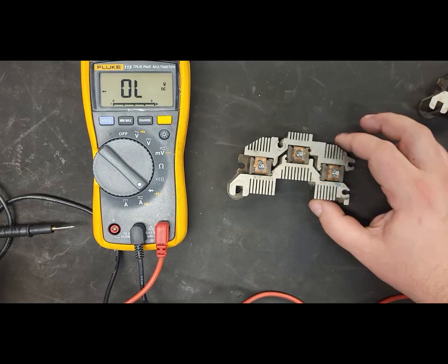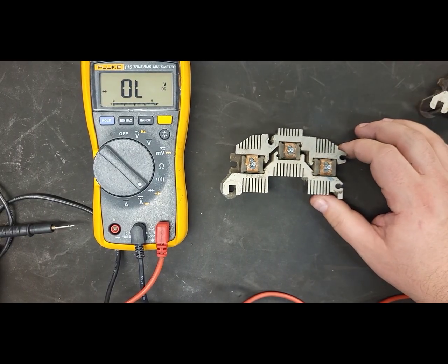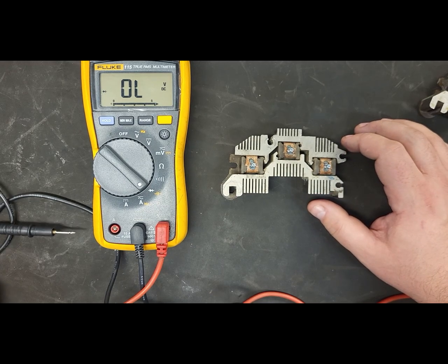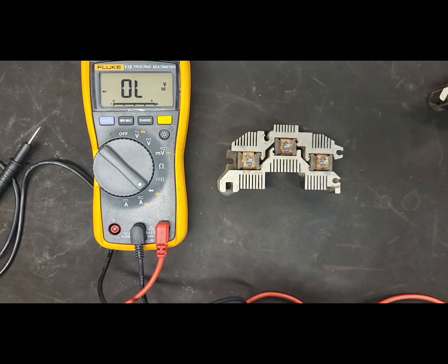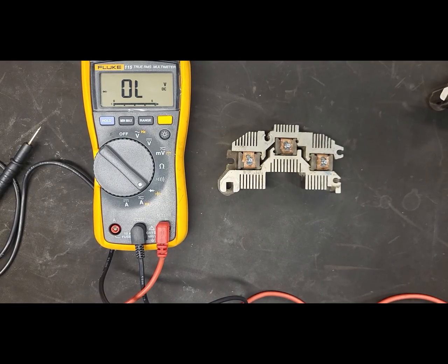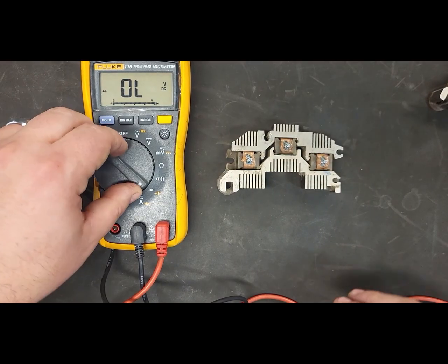Now with a shorted diode, the current draw through that diode is going to pull in a substantial amount of heat. I don't think that diode is going to stay shorted for very long before it decides to open up and burn up. With the shorted diode, we would still see the 60 to 70% amperage output loss. From the open condition, that would change to a 33% amperage output loss, which would still be a pretty substantial loss. We would identify that by doing a load test on the alternator.